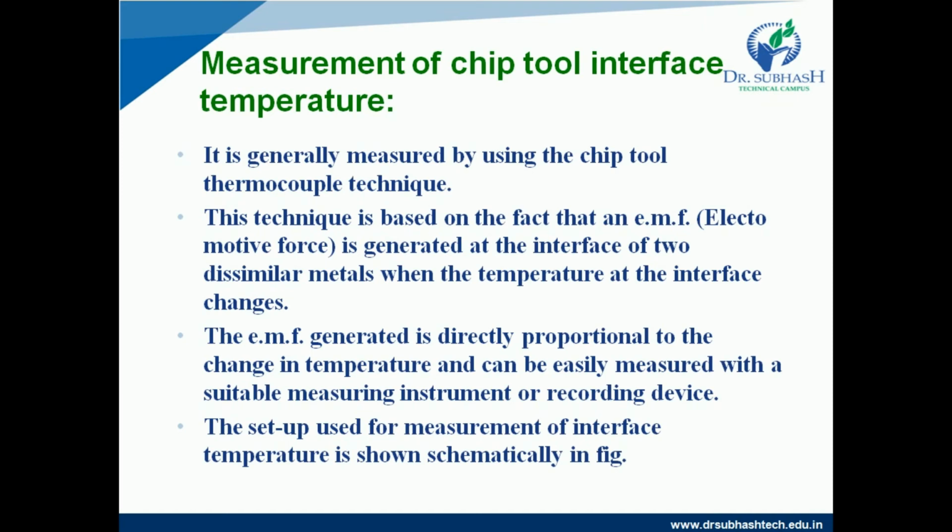In another way we can say, in the thermocouple, two dissimilar but electrically conductive metals are connected at the two junctions. Whenever one of the junctions is heated, the difference in the temperature at the hot and cold junction produces a proportional current which is detected and measured by the millivolt meter. So in machining, like turning, the tool and the job constitute the two dissimilar metals, and the cutting zone functions as the hot junction.